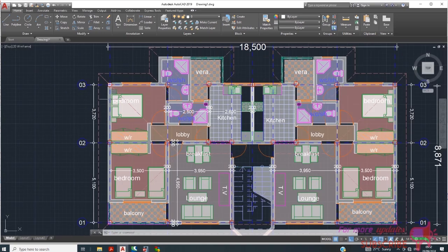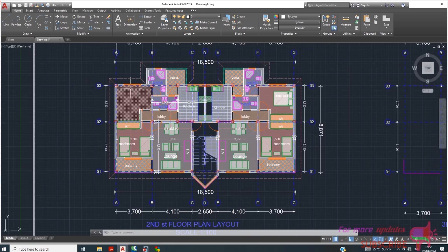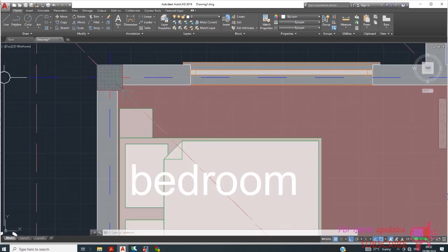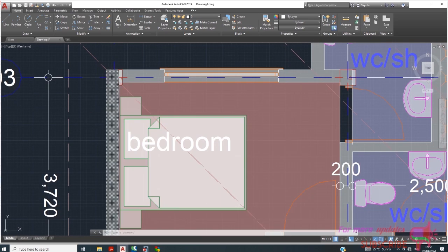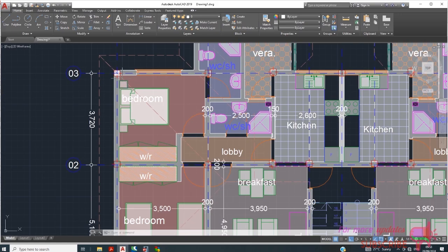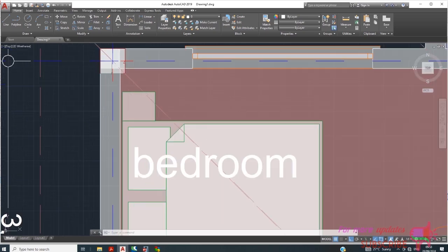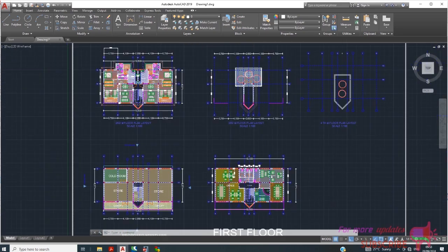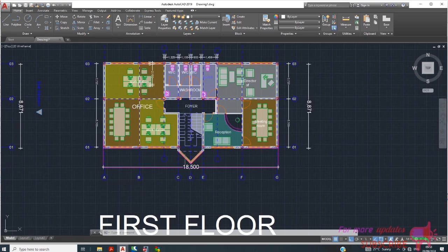Before you place your column, you can do the preliminary sizing. So you can use spreadsheets to do preliminary sizing of columns. But for me, I already did that. So I think we can just guess. I think the minimum should be not less than 225 millimeters each. That is about, I think, 8 inches. I will just go for 250 for this.